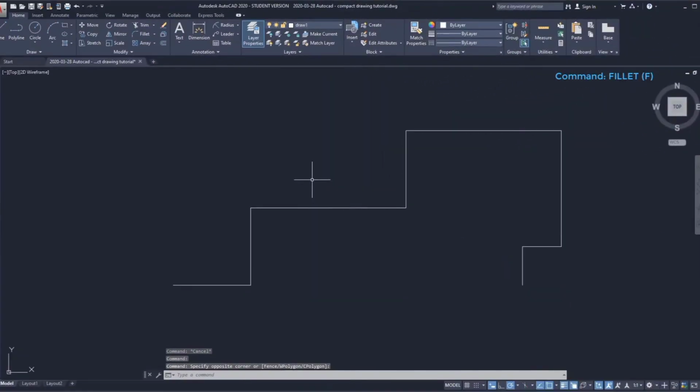I am going to show you how to use Fillet for all the corners in this polyline. It's really simple. Activate the command. Now it says radius 20. I leave it like that, but this time I want to use the option Polyline. Finally, I select the polyline, and you can see that the command applied to all the corners at the same time.